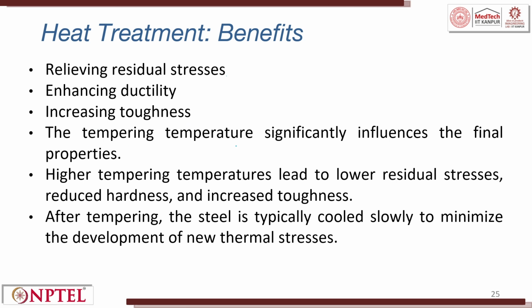The tempering temperature significantly influences the final property. Higher tempering temperature leads to lower residual stress, reduced hardness and increased toughness. After tempering, the steel is typically cooled slowly to minimize the development of new thermal stresses.